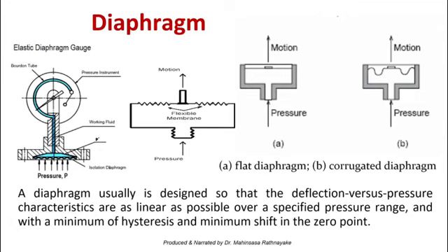Another fact: in the old days, they used metallic strain gauges with diaphragms, but it was not that successful. But nowadays, semiconductor materials or piezoelectric materials are used. That is how they overcame the problem I told you about with diaphragms. There is some problem with low output, because the displacement in membrane materials is fairly low compared to bellows or capsules. To overcome that, the technology changed the material into semiconductor, piezoresistive or piezoelectric materials. Then even though it has a small displacement, it has a high sensitivity, right? That is how they overcame the problem.